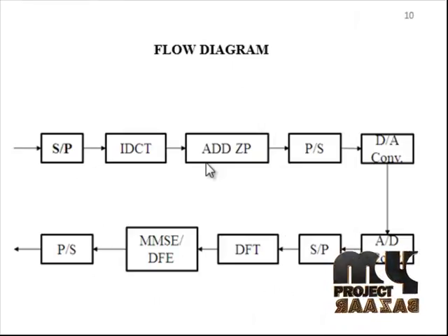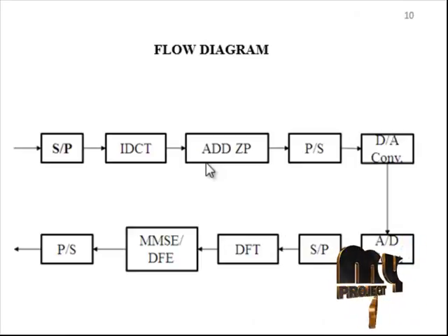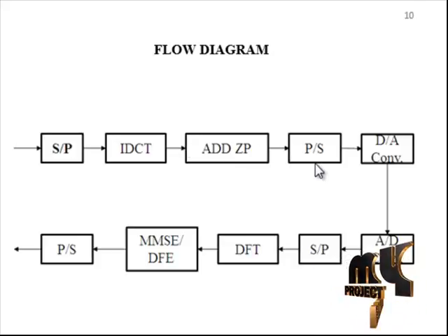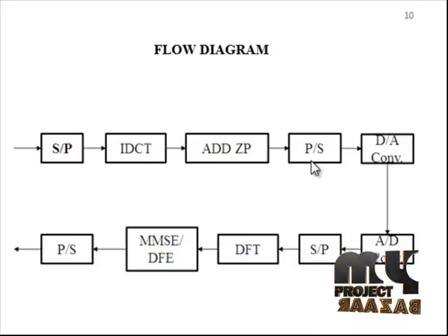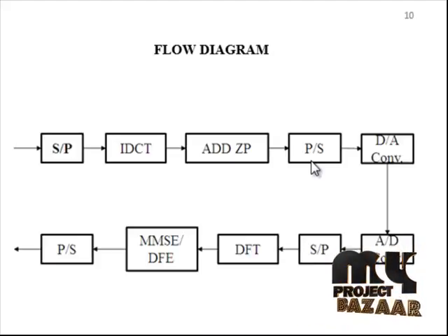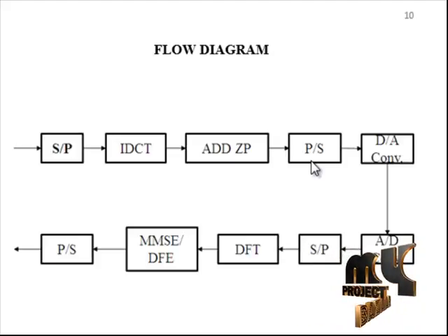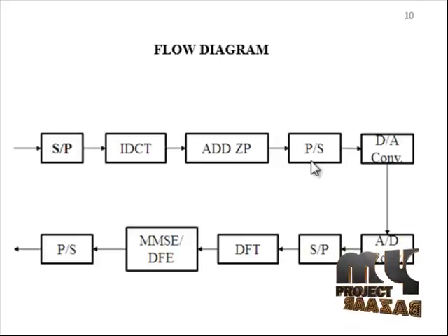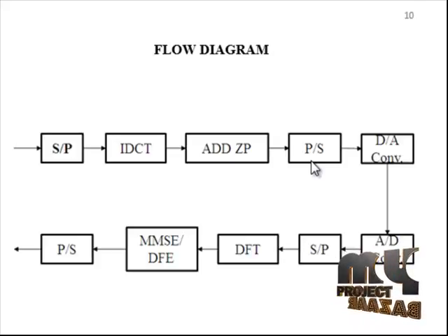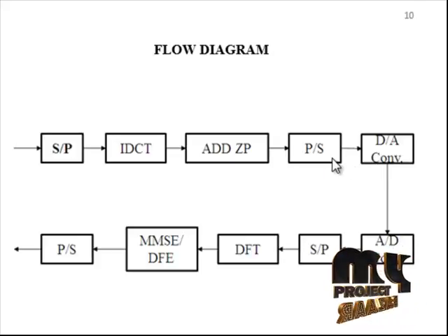Let me discuss the flow diagram for our process. Here we design the fast OFDM blocks. OFDM systems have some advantages for mobile wireless transmission as signals are robust against frequency selective fading. For digital signal processing applications, OFDM systems have become inexpensive and available in consumer products. The intrinsic design of an OFDM system prevents interference among the carriers, also called subcarriers. Inserting a cyclic prefix before transmission avoids intersymbol interference.